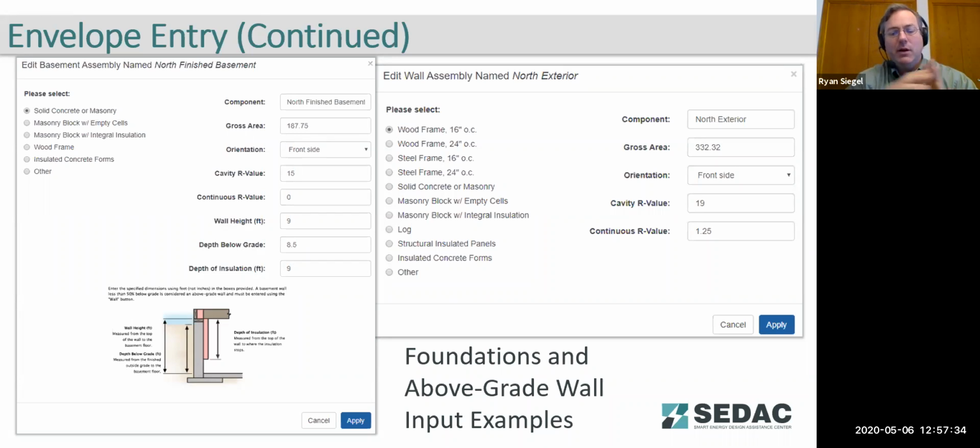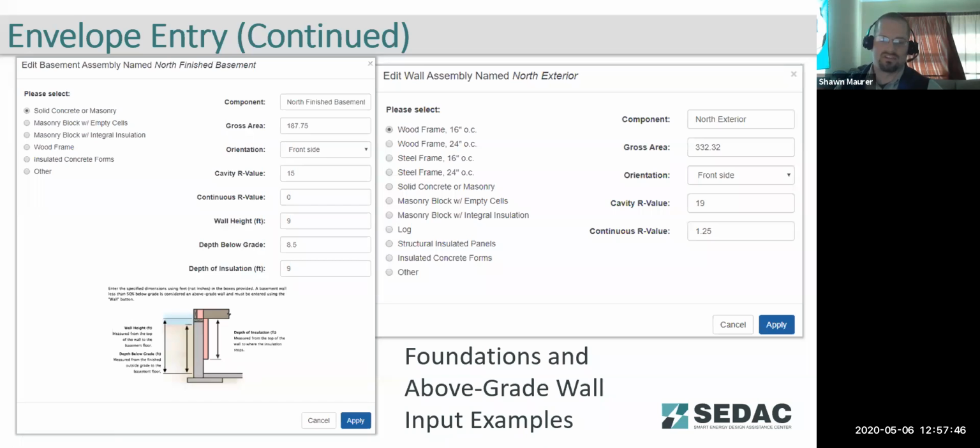So that does give you a few different input metrics. To further address that question, the Illinois amendments do allow for that insulation to stop 6 inches above the floor, where the code requires that insulation must go to the bottom of the floor slab, so it must touch that floor slab, or be 10 foot below grade, whichever is less. Just to clarify those insulation requirements.